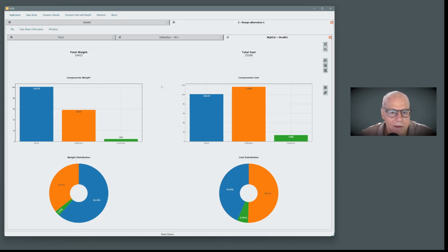This is done by taking the properties that are in the database and using the geometry to calculate the cost, and then using a factor that is in the database for each type of material, for stiffeners, for attachments, for sheet, which I defined here as I wished, but for every institutional company, the values can be used to reflect their actual costs for each type of component.